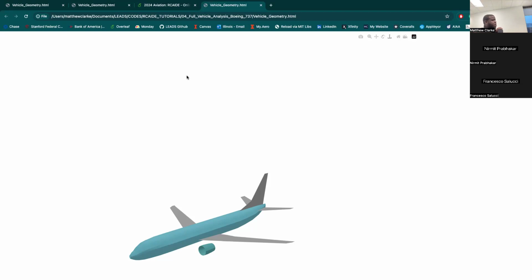So there are 2 options, but we choose the first one. What we do is create a surrogate using the VLM. We create a 3D data set of Mach number, angle of attack, and I think another term, and then we query that within the mission. It uses a vortex lattice method developed at Stanford, but it's based on work from McDonnell Douglas and Boeing prior to Boeing, basically.